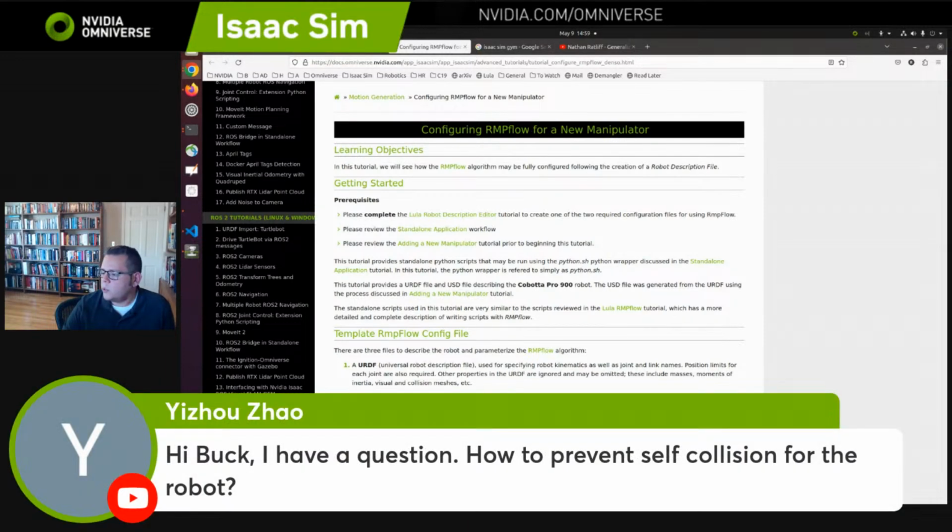Okay, there's this question about self-collision. I did address it briefly earlier in the live stream. The answer is we don't have a great way to do that today. If you missed that part of the stream, rewind to where I talked about collisions. Body cylinders, I think, is the term that we use. If you have a single arm and you just want to avoid self-collision, so let's say a single serial robot avoiding collision with its own base, you can use that body cylinder mechanism to avoid those collisions.